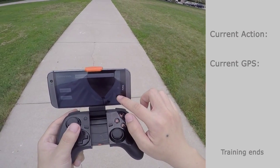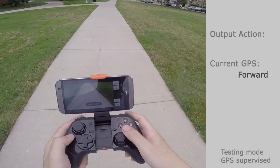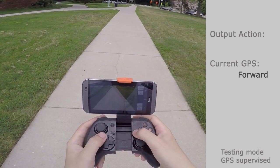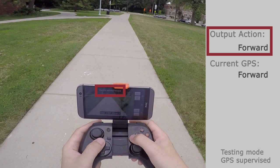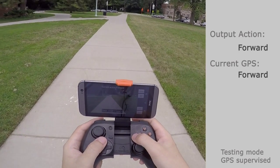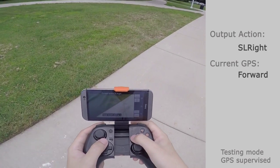I switched the mode to real-time testing mode. Change the GPS signal to forward. This time, we do not supervise the action of the network. Instead, we will follow the network's output at the upper region of the screen. Due to reflections and glares from the sun, we map the output action to the right-hand side of this video. As you can see, the network learns to follow the road with satisfactory performance.